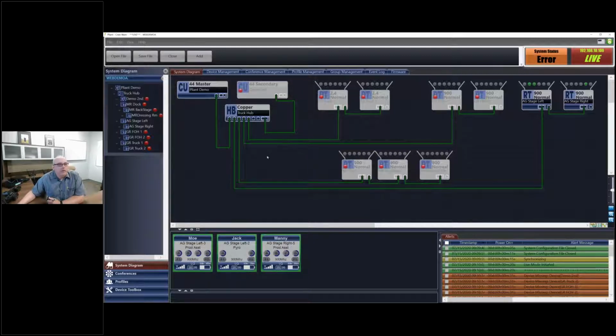So anyhow, that's also fiber to keep in mind, as we've mentioned, does require a power supply. So if I did run fiber out to this transceiver here, you would need a local power supply. In this particular case, everything could be done PoE. The only exception to that maybe would have to be the hub, because you're running a fiber connection here, you would locally power that hub. And we typically recommend you go ahead and locally power the hub, although in a smaller configuration, it would not be a requirement.